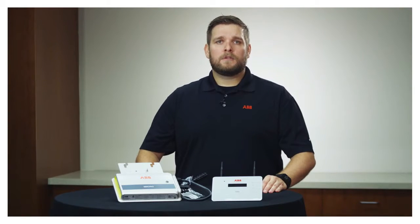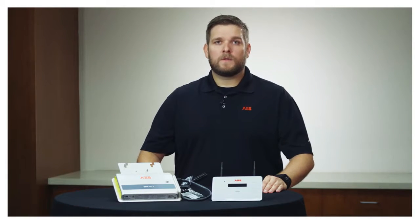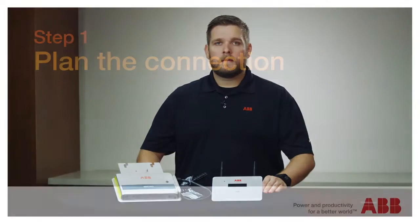The CDD is required to commission the ABB microinverter system. One ABB CDD can monitor up to 30 microinverters. For systems with more than 30 microinverters, additional CDDs will be needed.